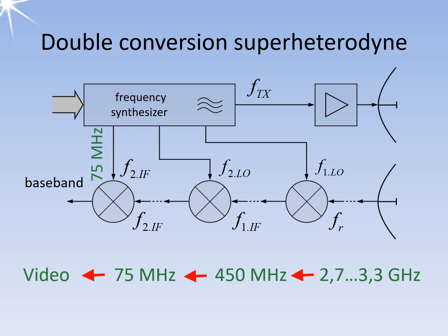All of these frequencies required for down conversion, like the transmit frequency, should be generated from a single source with highly precise phase consistency. Only with this level of coherence can the radar effectively measure Doppler frequencies.